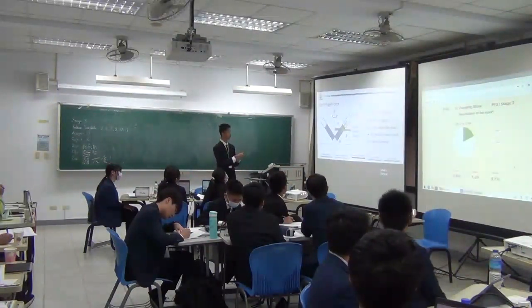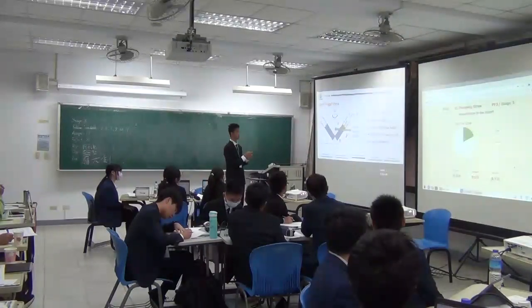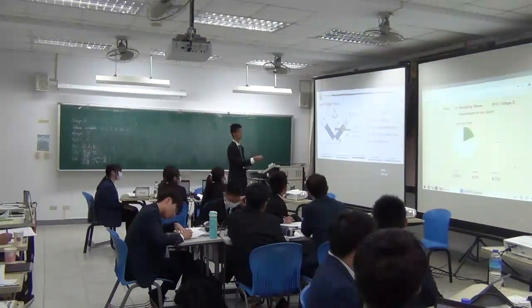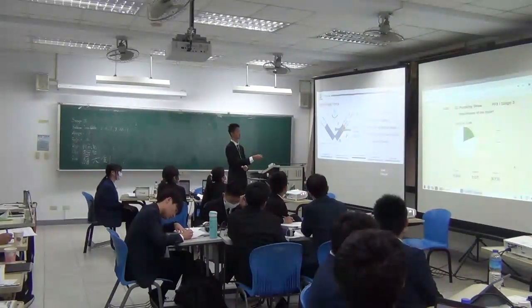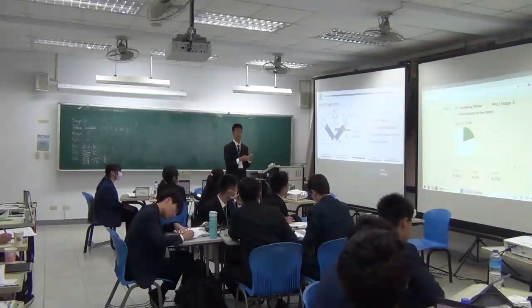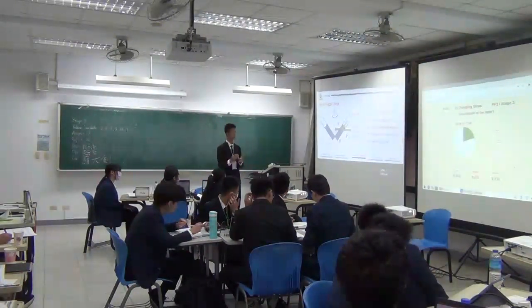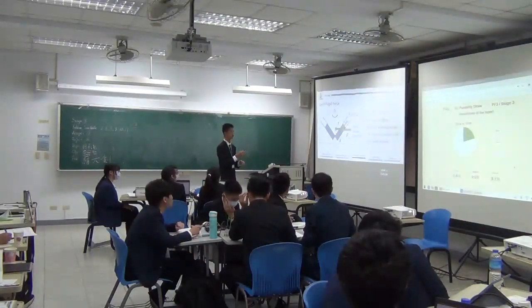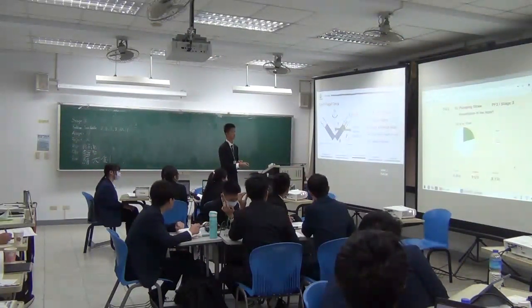let's consider a very small water segment, and this segment is accelerated due to the centrifugal force, which is given by this equation. And we see that it is proportional to r, which is the radial distance. Which means that water at higher positions will tend to accelerate faster. Now it's because of this difference in acceleration that we see water droplets coming out and not a water stream.